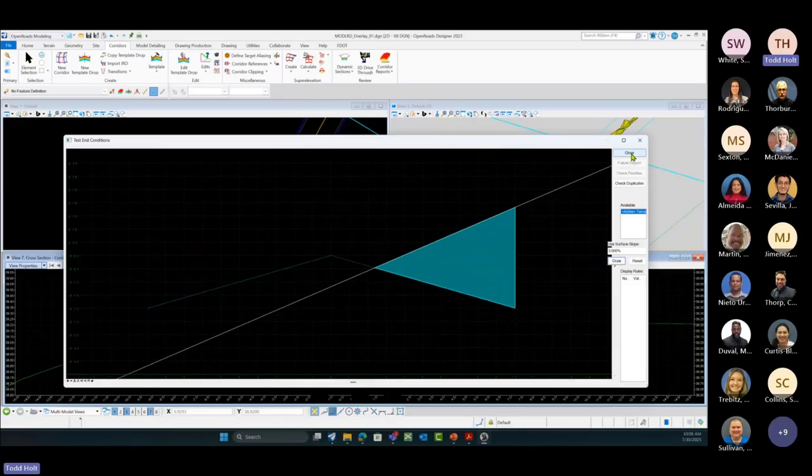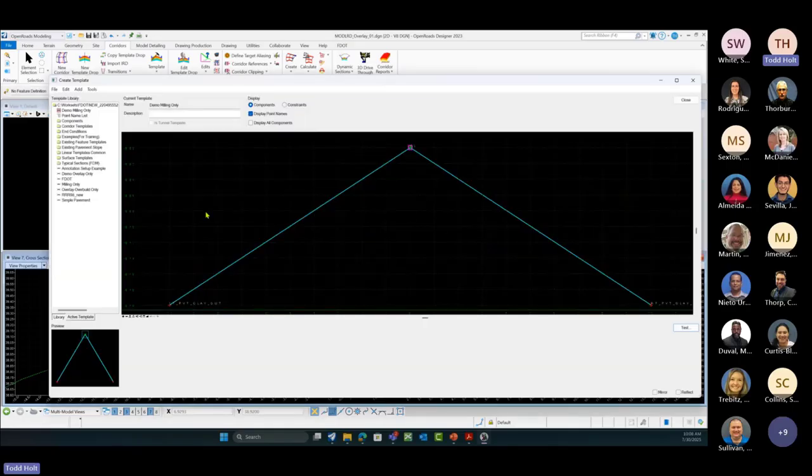Right, so we have those in there and close. So there we've built our 2 millings and our overlay. Right, so now that we have these 2 separate ones, we can apply it to this simple template or the simple pavement. So here we have our pavement, that's simple. We're going to make a copy of this and we can see what it's going to look like if we just have milling or if we just have our overlay. And then we'll do a combination of those 2 different ones, because we might have that solution within there.